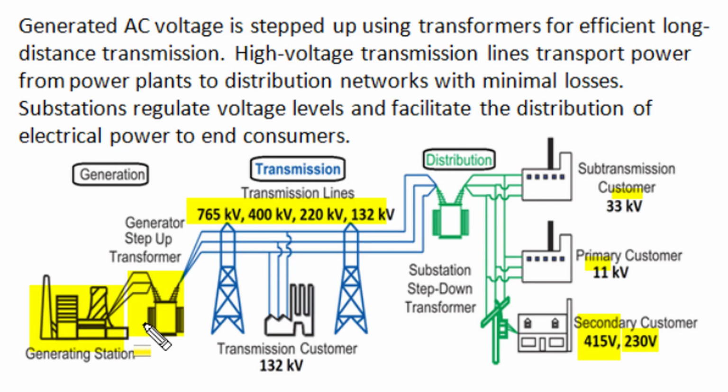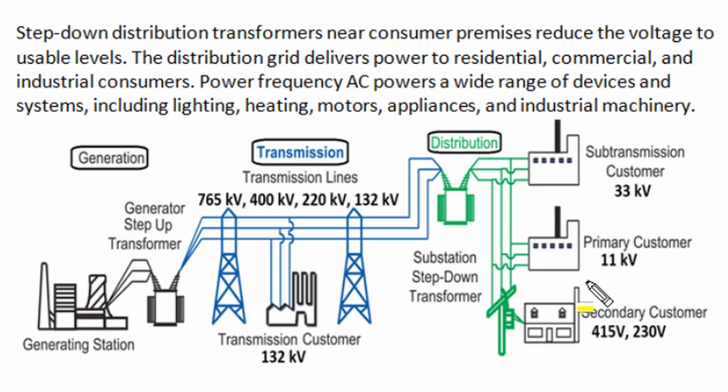This functioning of transformers, step up near the generating plant and step down near the consumer, reduces the cost of transmission and distribution system, and increases its efficiency and performance. In these transformers situated at substations, we have facility to regulate voltage level to ensure standard rated regulated voltage supply to different consumers. Step down distribution transformers mounted on poles near consumer premises reduce voltage level to a safe working voltage level, and we supply electrical power to residential, commercial and industrial consumers.